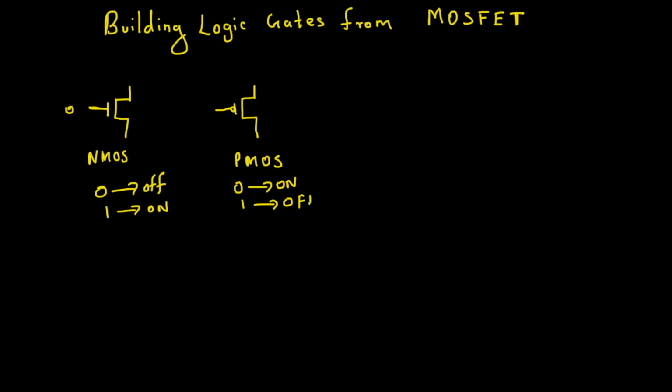If you look at the diagram, the combination of these two, NMOS and PMOS, makes CMOS. So for example, we can look at a CMOS that looks like this. We can attach NMOS like this and PMOS, and we can see the behaviors. Let's say this is VDD and this is connected to ground, and I attach an input at the gate.